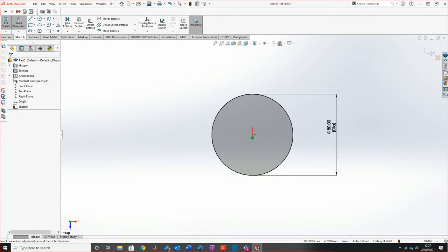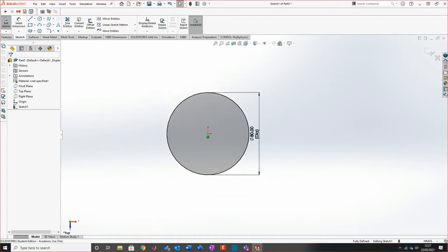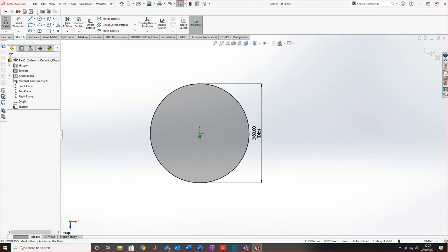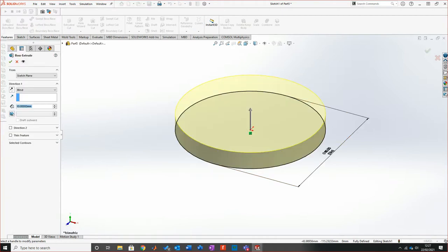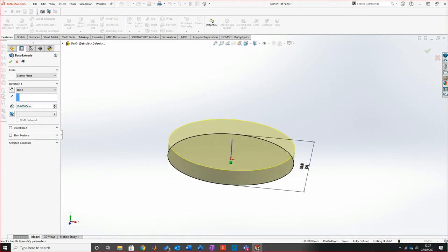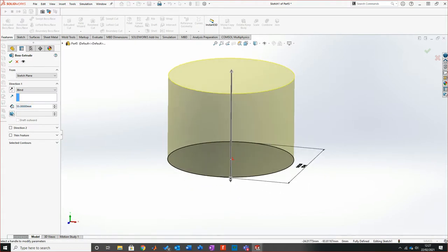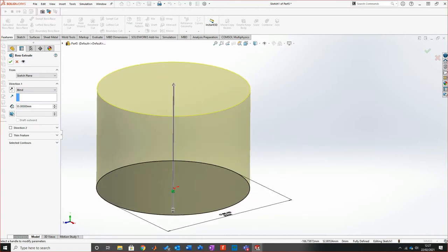So then you'll see here that on the right side, it's instantly marked as dia. If you are going to do a lot of automation on these types of systems, if you are going to increment an automated method, using the named dimensions saves your ass big time. So what I'll do from here is then go extrusion, and come to here, and then I will click onto OK.